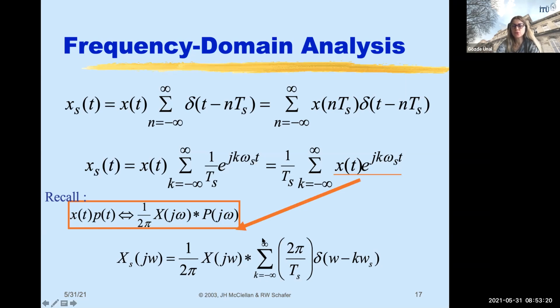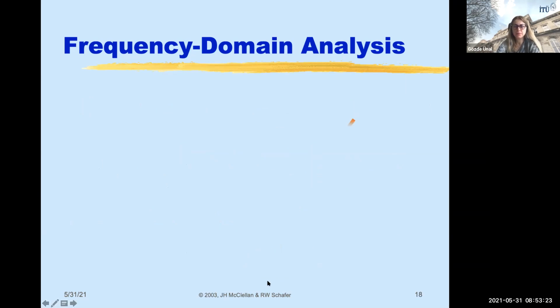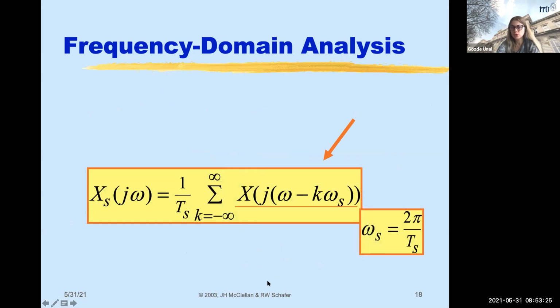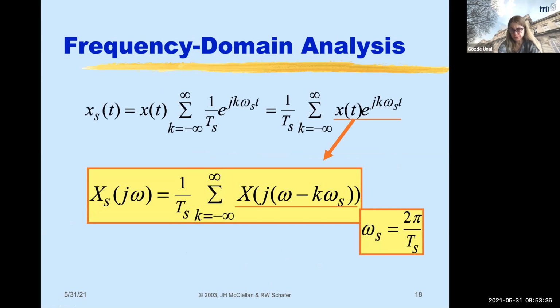So, even if you are maybe lost at this point, don't get lost. Just catch up here at this point. This is actually the Fourier transform of this periodic impulse train. Actually, this is a little bit more general. You can see that this is for a periodic signal whose a_k, or Fourier series coefficients, are 1 over Ts, which is of course the periodic impulse train.